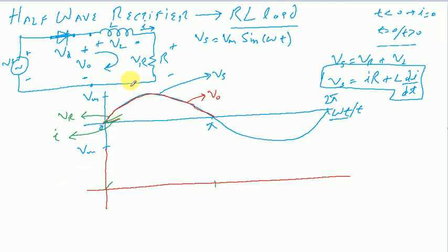But as gradually the inductor starts to build up, or store, energy, during this time the voltage across the inductor is gradually falling and the voltage across the resistance is rising, but the net sum of the two voltages is always equal to the source voltage. We can also rewrite this equation, this one, in this form as well.